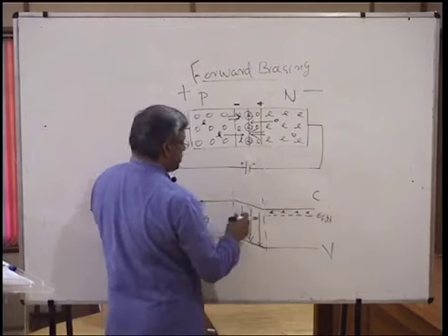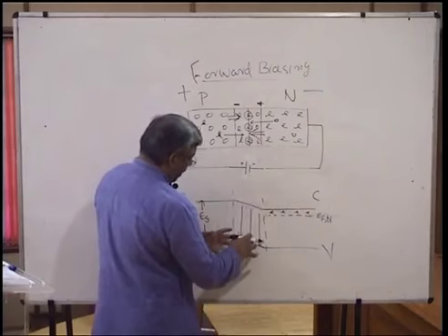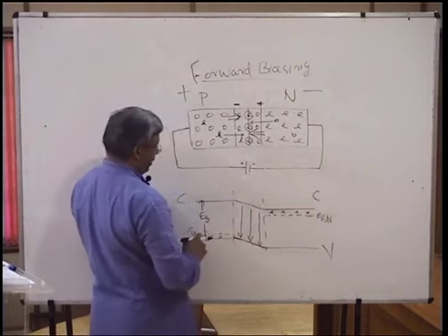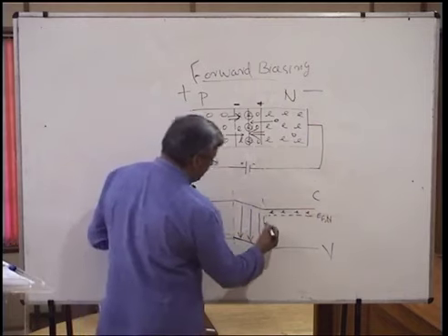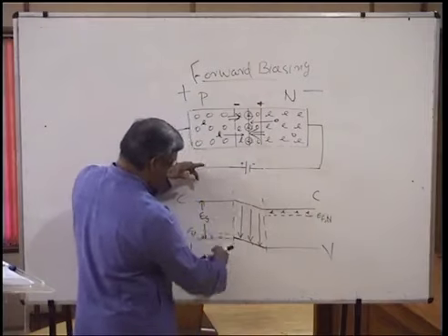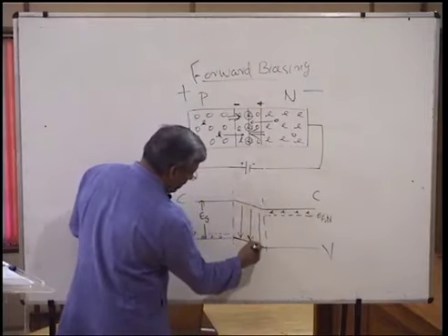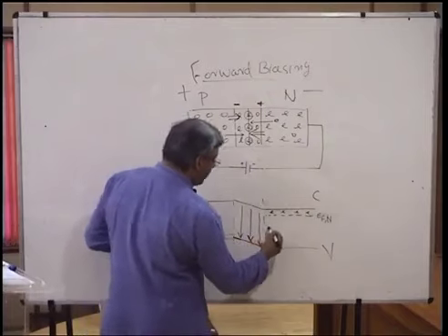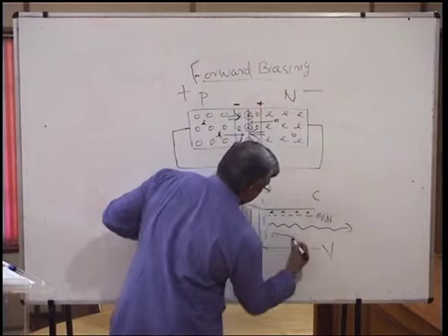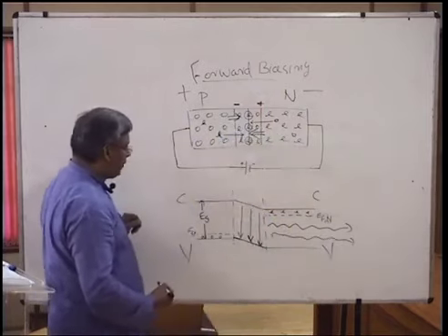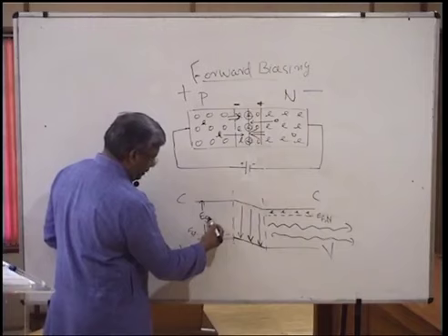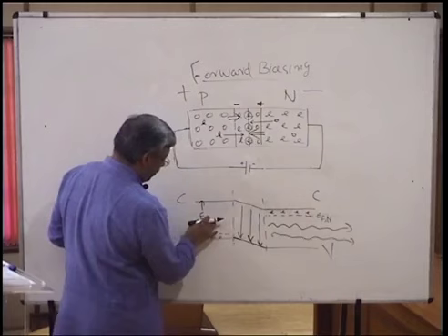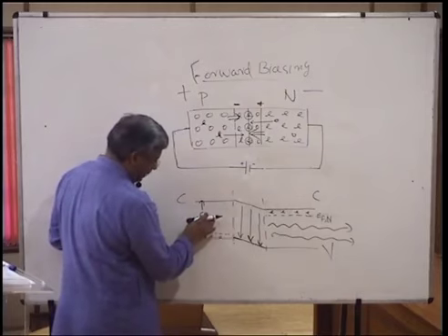The electrons in the conduction band of the depletion layer will be recombining with the holes in the valence band of the depletion layer. And as a result, there is a de-excitation happening right now. You can imagine there's a de-excitation. That's why I've shown this with the downward arrows. De-excitation is happening, and then a light will be coming out, which will depend on the energy gap. Not on the internal potential barriers, but right on the energy gap.